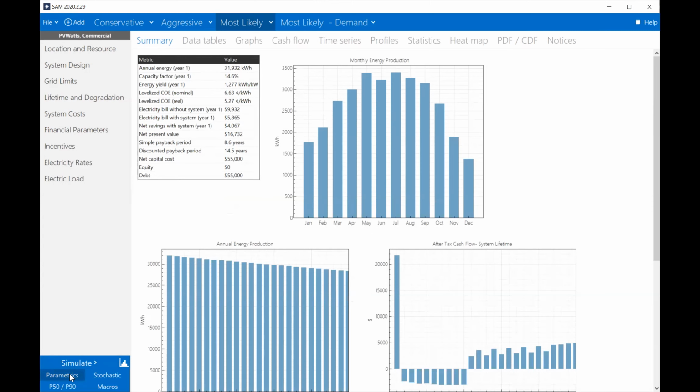John, go ahead, Eric. Yeah, and at 13 cents a kilowatt hour, you're looking at $120 to $150 a year just for that. While it doesn't look like a big difference in that chart, well, guess what? That offsets your annual O&M. And look at my winters. They were much lower. Now my winters look a lot better because I raised that tilt angle and changed it to facing south versus facing southeast. So that ground mount may be a better deal for this particular application.